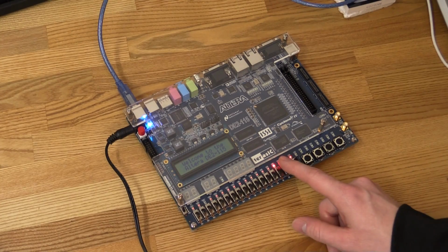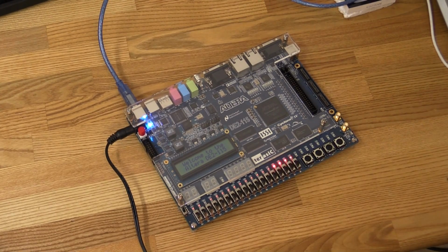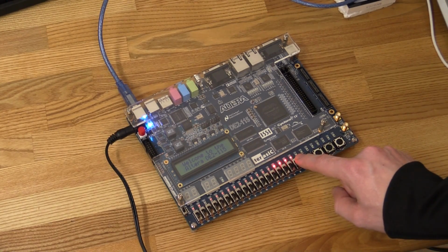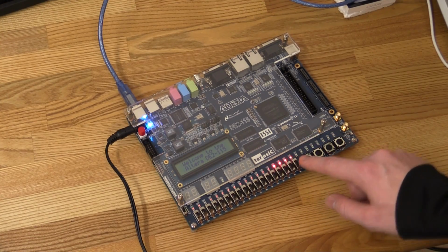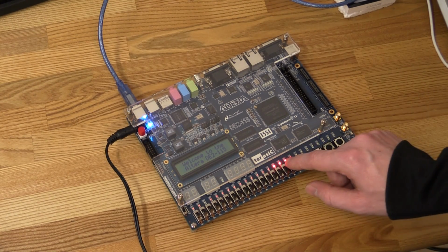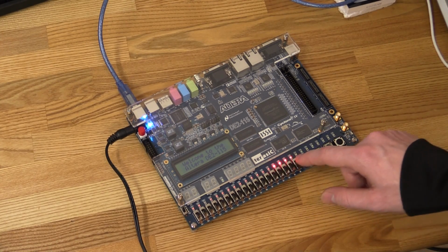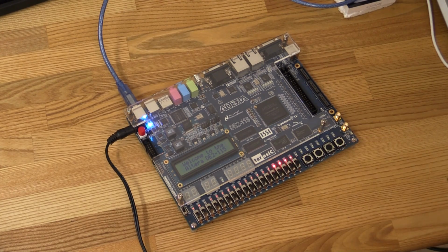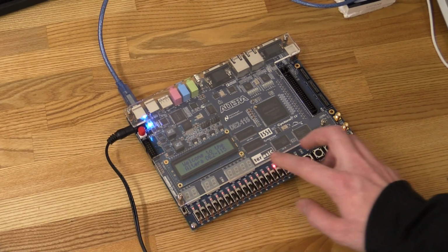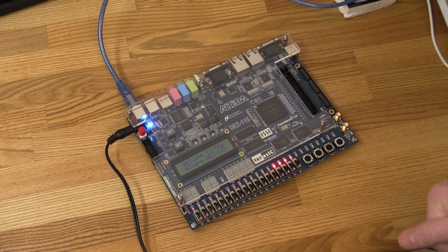I hope it lights up on the camera. But you might be able to see our problem here. Our counter doesn't seem to work. But actually it is working, it's just this LED is flashing at 25 megahertz. And the next one is 12.5 and 6.25 and so on. So we need to do something about that. The easiest way for now is just to extend the counter a whole lot and then only use the last bits, so they will be toggling a lot slower. So let's go to the computer and see how we do that.